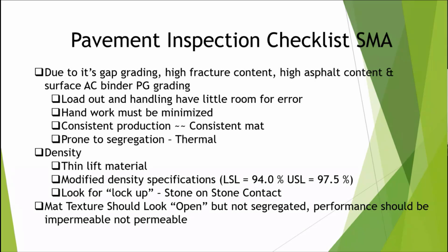But you have to watch out for these things in the field. It's tougher to compact. If it's tougher to rut, it's going to be tougher to compact. So you have to think differently when you're looking at your screed, your paver and your rolling operation. In load out and handling, you have little room for error. This high mastic makes it really sticky. Basically, handwork is damn near impossible. When you start lutting this stuff out, it's like trying to spread peanut butter on a smooth surface.